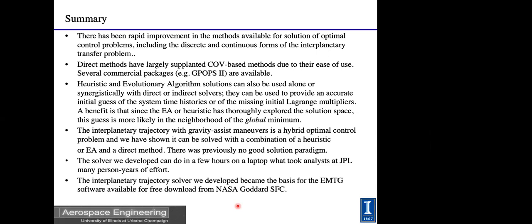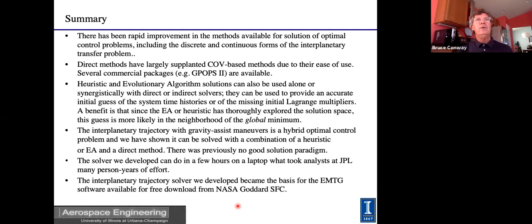And the second question is, I know direct methods for things like low thrust trajectories have been criticized for the numerical issues dealing with the very small numbers involved and the differences in magnitudes of variables. Have you had issues with them? And off the top of your head, what are some best practices that you've used? No, we haven't really had much problem. What you generally want to do with these kinds of problems, the NLP solvers are much happier if everything is roughly about the same order of magnitude.